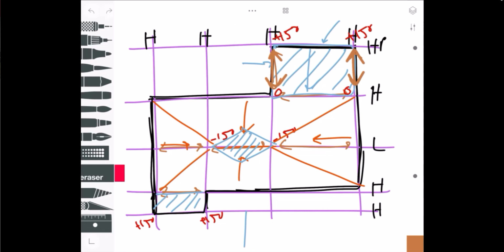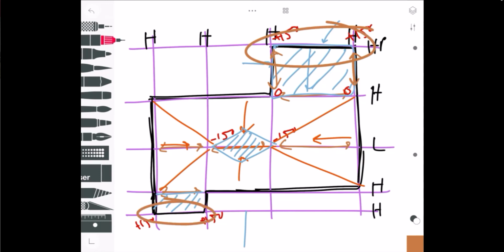You just have to look at maybe your cladding. I think the only reason you maybe wouldn't want to do that is, if you have an eave system, you'd have a deflection joint underneath the beam. So it's nice to keep that joint at a consistent height, but it could still be done actually. So yeah, that would probably be a good option there. It's just you wouldn't have a level structure around the whole perimeter. It'd be a little bit higher at this end and a little bit higher at that end, and that would work as well.